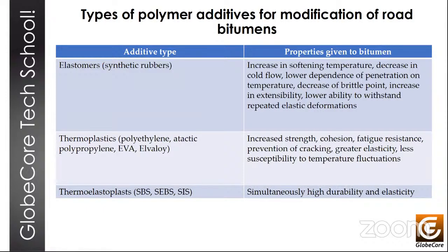Flexible and resistant bitumen coatings are obtained by adding styrene butadiene rubber to bitumen. The most widely used polymers are of the SBS type. These SBS polymers are used mostly because of their ability not only to increase the strength of bitumen, which is achieved by other types of modifiers, but also to give the polymer bitumen composition elasticity, which is a property inherent to polymers, at rather low concentrations.